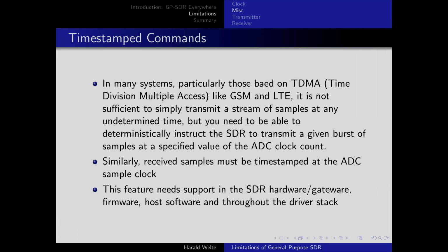One other important requirement when it comes to SDRs is time-stamped commands, or time-stamped transmit or receive. That means that it's not sufficient that you just create some samples on your PC and stream them out over the radio, but you actually want to precisely define at which particular point in time a given sample, which represents the start of a burst, is transmitted over the radio, and vice versa.